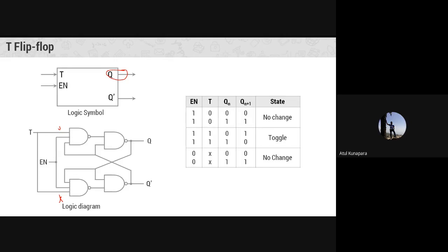It will remain the same. But in the D flip flop, you have the advantage of no invalid state, because you are combining both the inputs R and S together into a single input, that is the data input, so the invalid output state can be removed. It removes some restrictions in your circuit design. So that is the advantage of the D flip flop, and if you compare D with RS, you get this point of comparison, right?